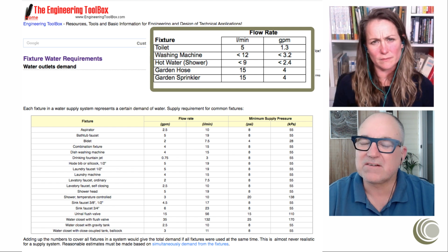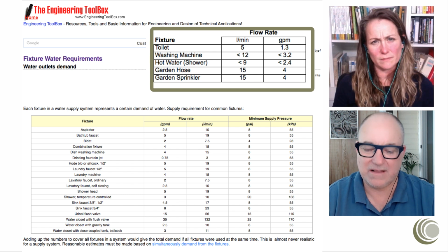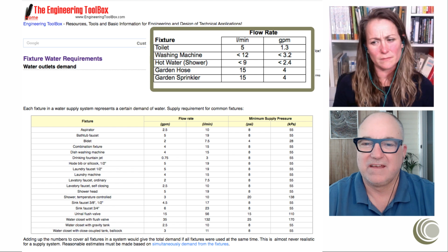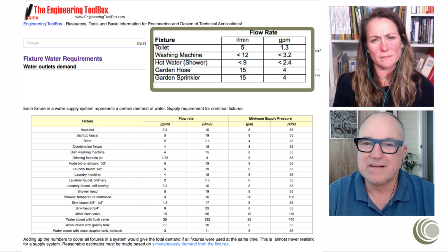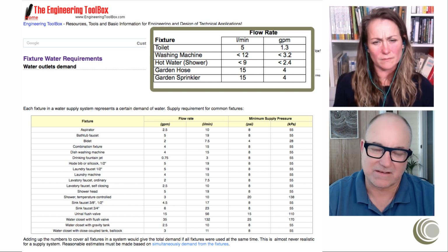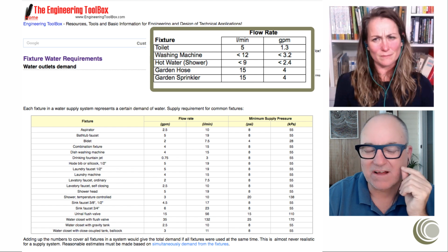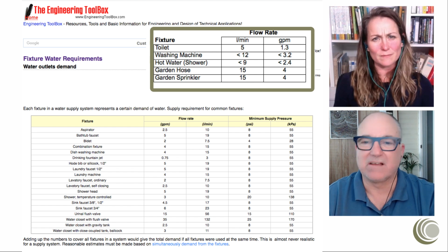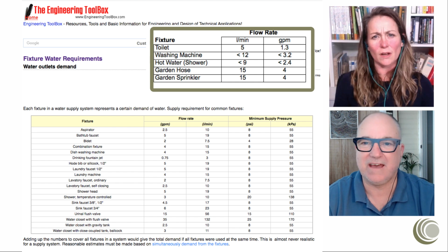So also something to watch out for: when we first set up our city rainwater harvesting system well over 20 years ago, we had this crazy plumber who put lots of bends in the lines. In fact he was crazy about bends, I think. So if you've got lots of bends in your line and you've got long delivery lines, there'll be losses in pressure and flow rate supplying your house.